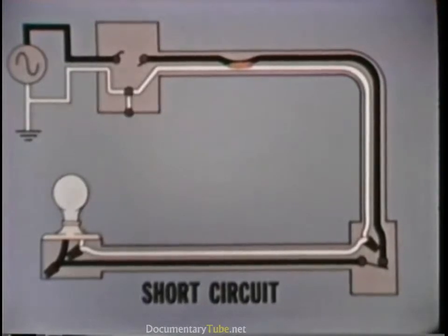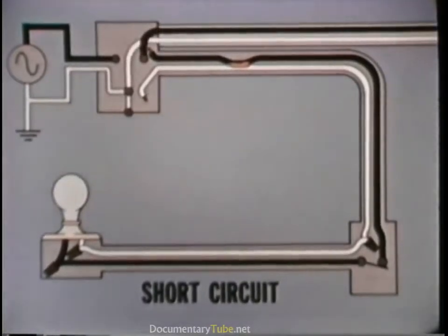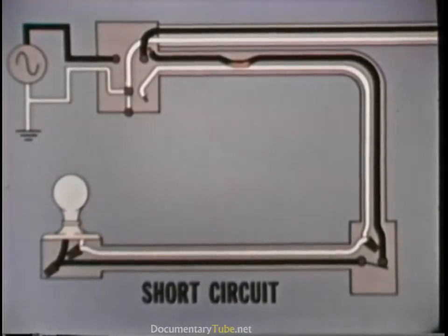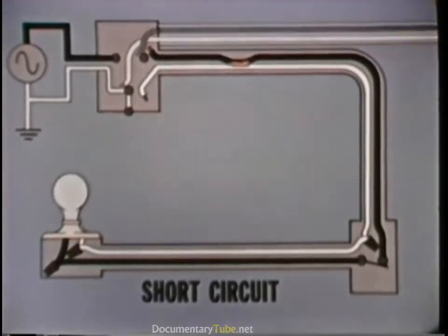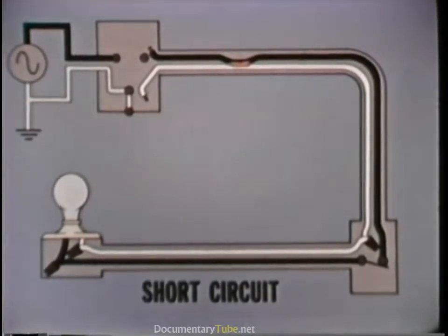To check the wiring safely, disconnect the conductors from the power panel. For the hot conductor, this is normally done by removing the fuse or opening the circuit breaker. However, if more than one circuit is controlled by the fuse or breaker, the conductors must be physically removed from the power connection and separated. Since a short or ground is suspected, remove the other elements of the circuit by opening the switch and removing the bulb.